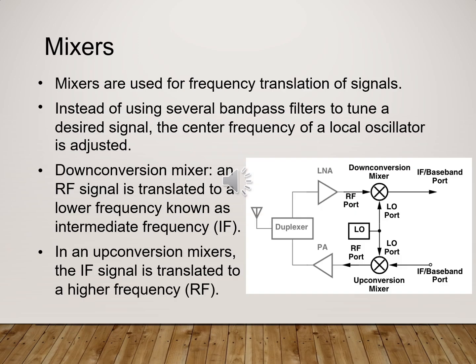Now, mixers. In electronics, a mixer or frequency mixer is a nonlinear device that creates new frequencies from two signals applied to it. For example, a key component of a superheterodyne receiver, as we see in lecture 5, is a mixer used to move received signals to a common intermediate frequency. So mixers translate the frequency from one band to another.